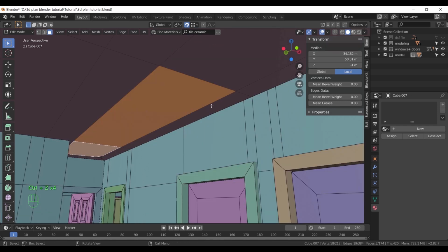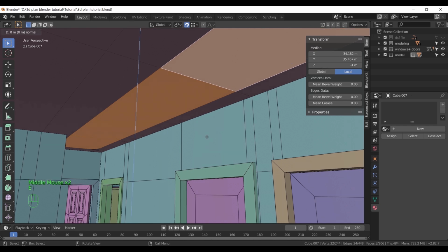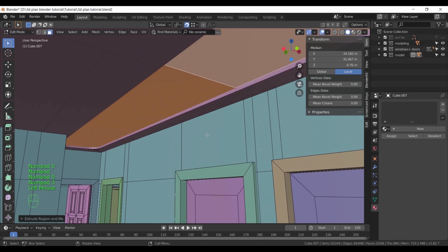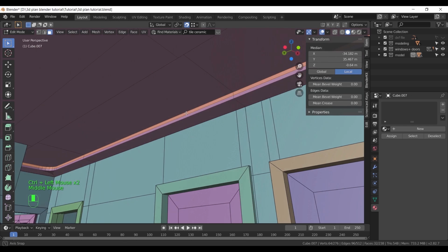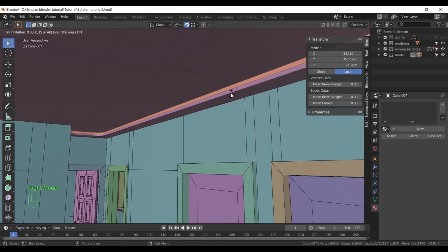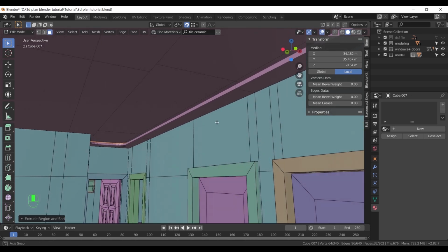Now select those faces from inside and extrude them up a bit. Hit Shift R to repeat the last process in the same value. I did extrude them by 3 cm, then with Ctrl+, we can grow selection like shown. Deselect the top faces, and with the right mouse button, choose Extrude along normal to push those highlighted faces inside the ceiling.